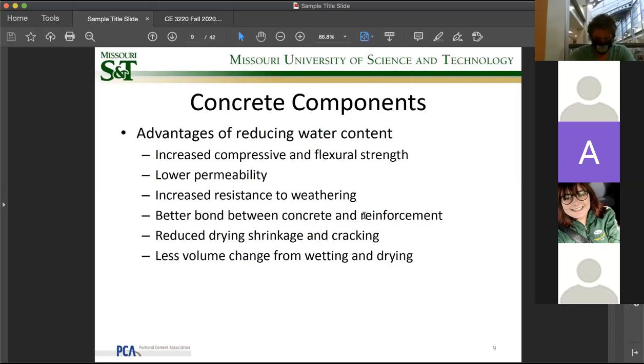So naturally, we have less of a freezing effect, as you all know from Physics 101. When water freezes, it increases in volume, right? The ratio is 11 to 10, 1.1 volume. So you have fewer pores, less intruded water, and so less volume inflation, less volume change. So it has better weather resistance, okay?